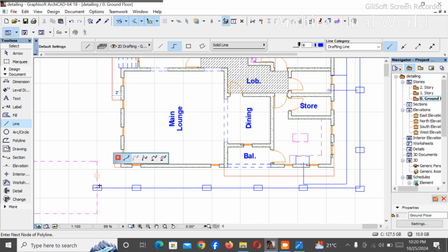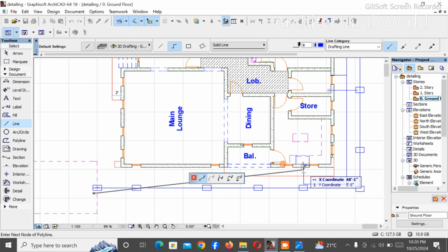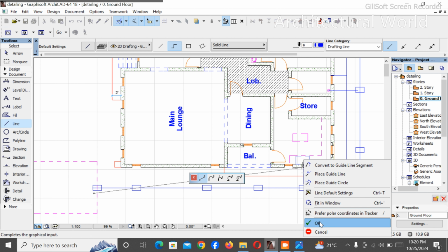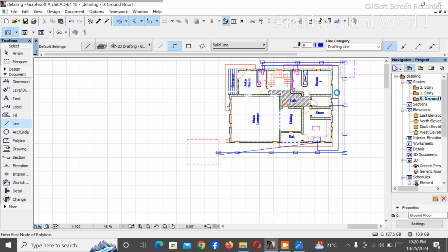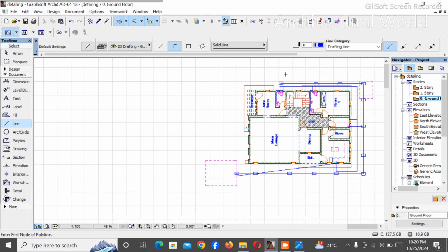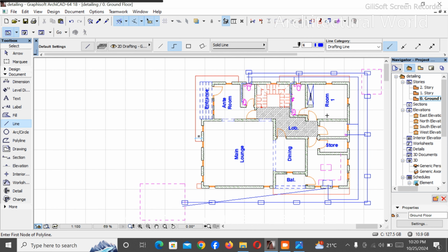You calculate the slope one way down to this part. And you have saved yourself the cost of all these chambers and wastage of pipes. Secondly, if you are doing a chamberless design, always make use of 6 inches. Don't use any size other than 6 inches, always use 6 inches for that, in case of blockage.